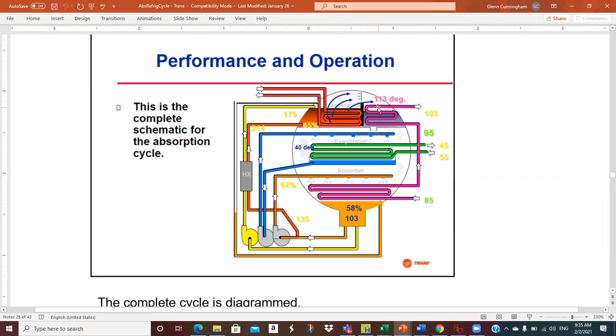where we've got cooling tower water inside tubes, and that's going to condense. Now this is at our high pressure, about 1.3, 1.4 psi-A, and it condenses, and we pile up some liquid water over here in the condenser. Then we have these orifices, and this is the pressure drop from the high side. This is high side pressure over here, and this is low side pressure in the evaporator. So this is where it drops to like 0.12 psi-A.